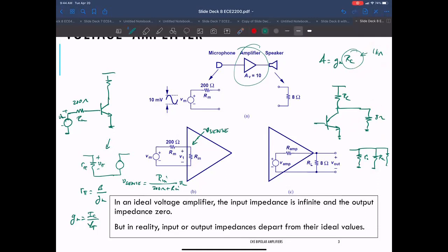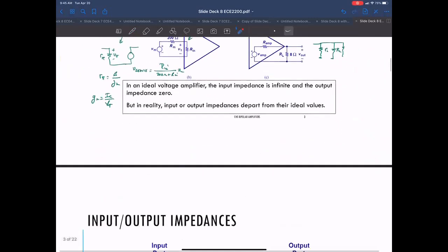So by sticking this in, your output resistance has gone from a kilo ohm to around 8 ohm. And so your gain has gone down by more than a factor of 100. So you can see this is a pretty tough case of driving a speaker. Again, that's a difficult load to drive, but it's an important part of our consideration when you're designing the amplifier.